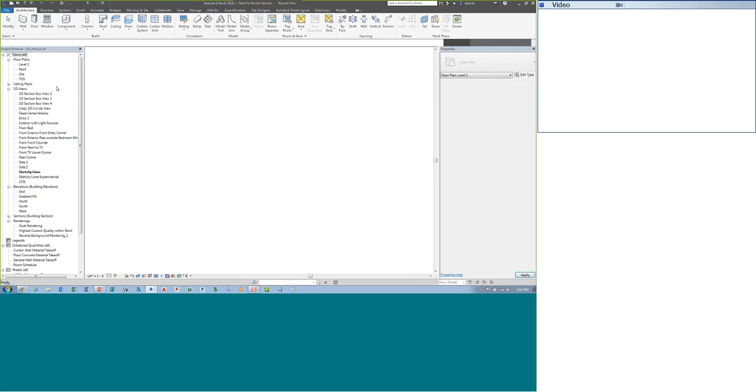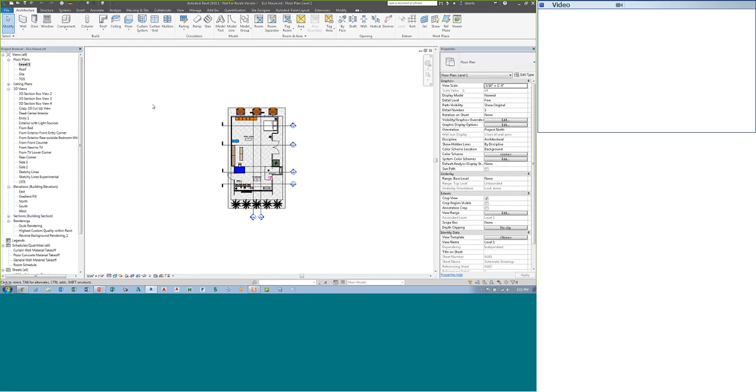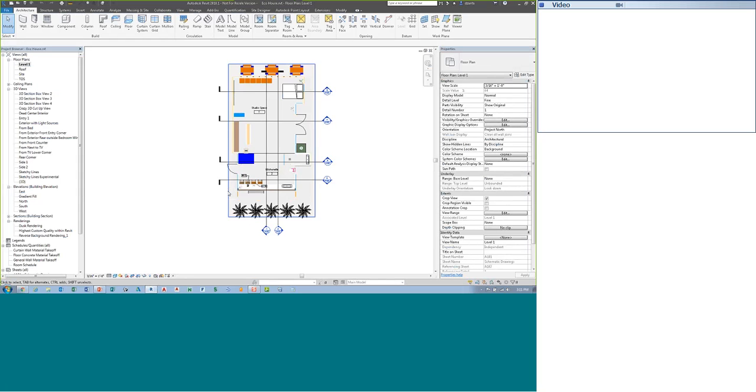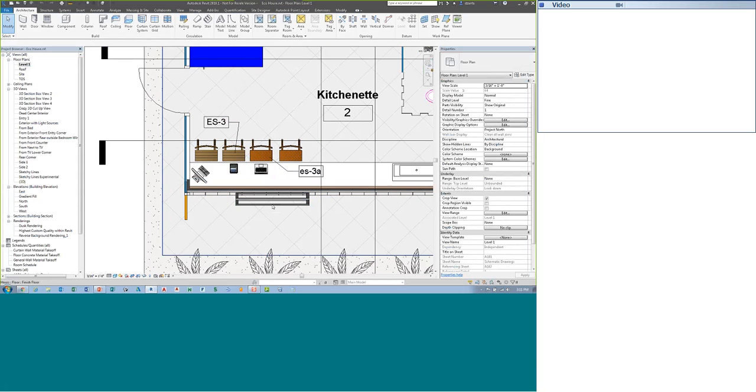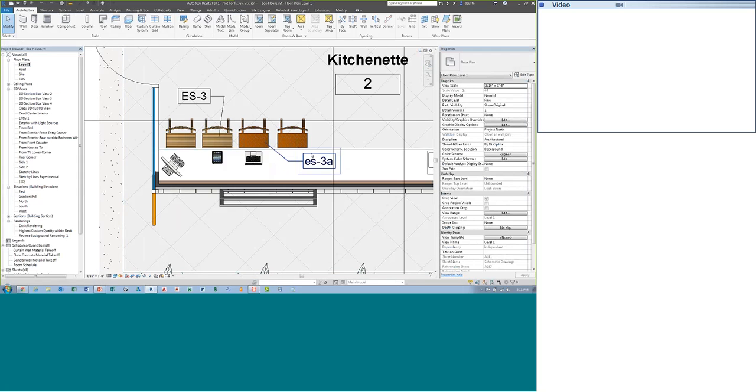Okay. And then lastly, if you're working on a project, let me look at a bigger file or something. This is kind of a neat tool that they introduced, I want to say 2017, maybe 2016 R2 is the earliest they introduced it. But let's say you're looking at this area and saying, well, I really want to look at just certain things in 3D. What you can do is I'm going to uncheck select elements by face. So I can do a window crossing, and just this right here.